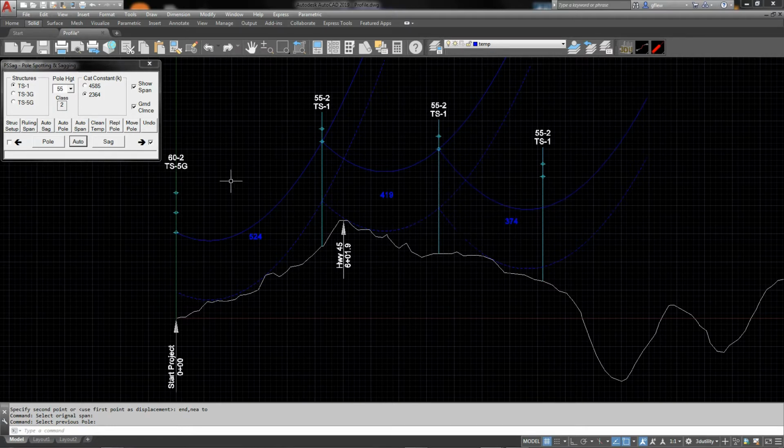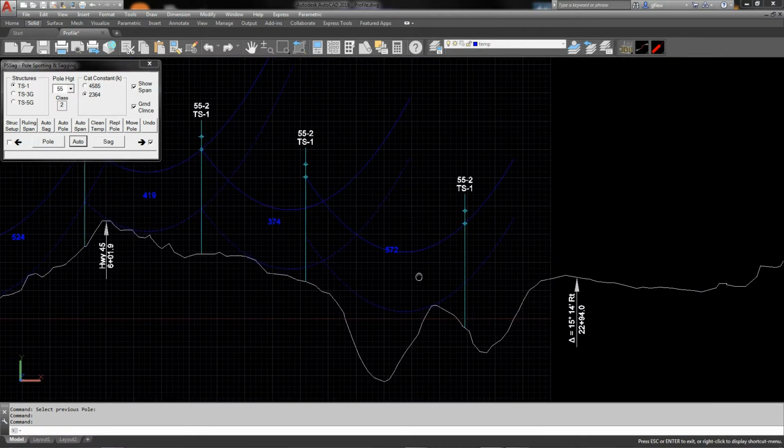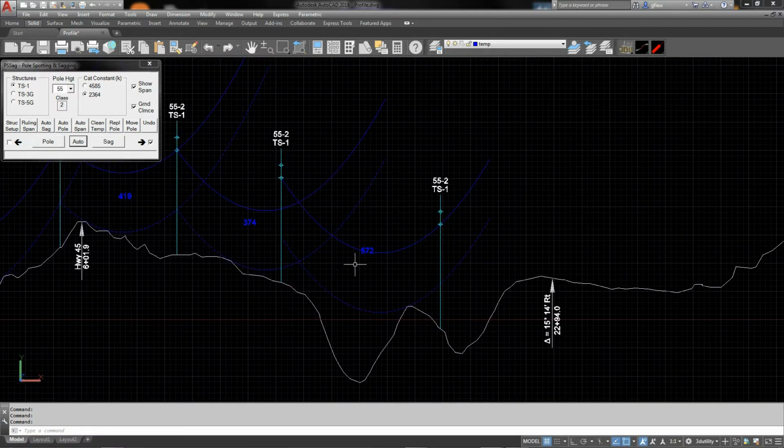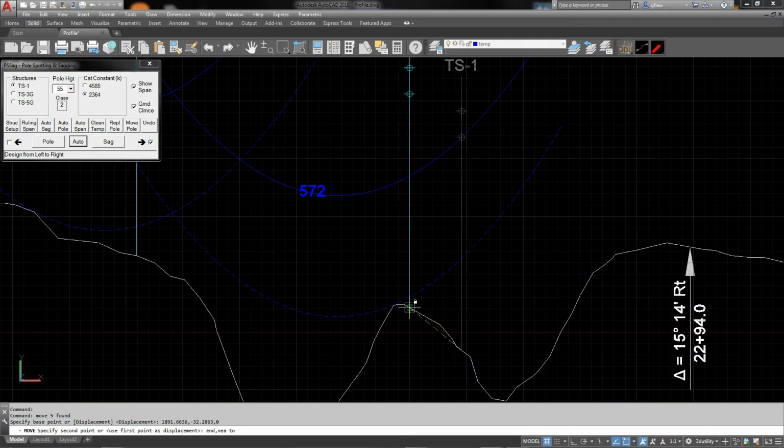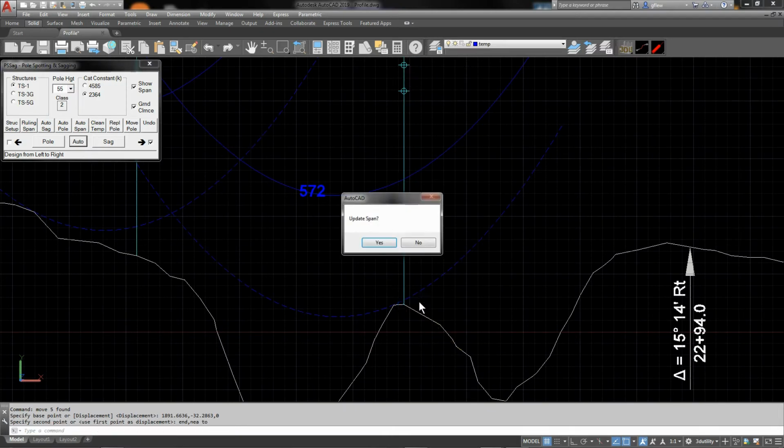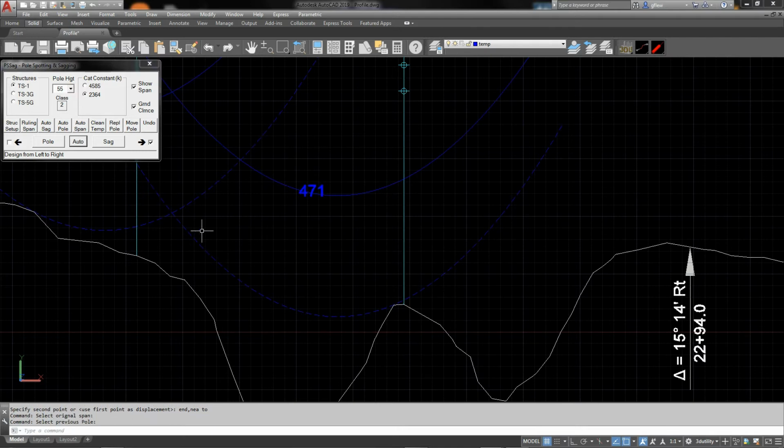So moving on, we'll go back and hit the next auto design, and again it remembers the last point on the pole. So even though I move the pole, it remembers its location. And once again, we have another that's on a rather steep slope, so we'll move that again. But again, this is just a matter of using your own engineering judgment to find these optimal locations.